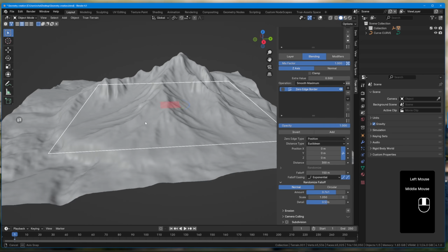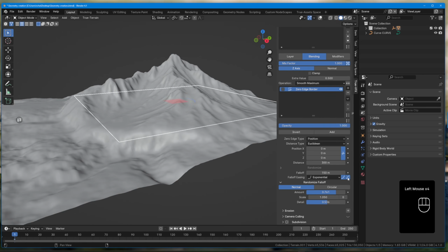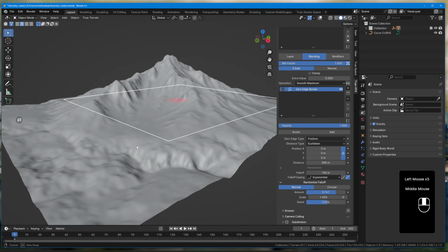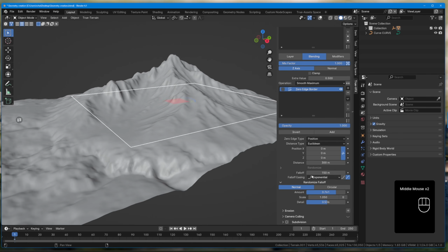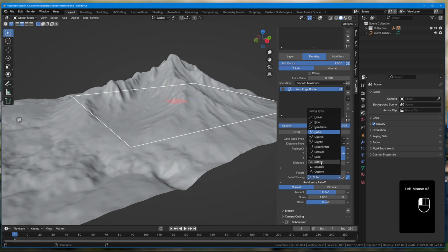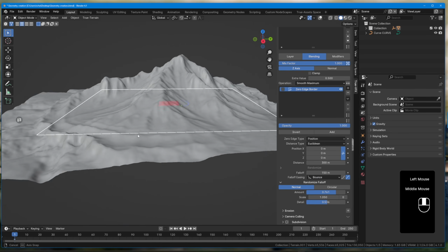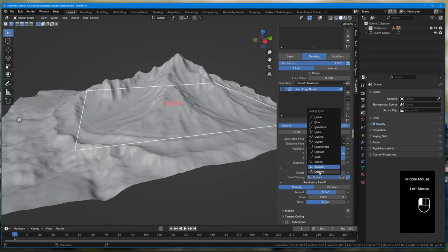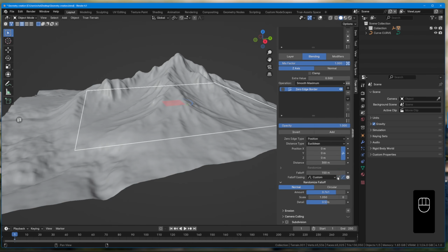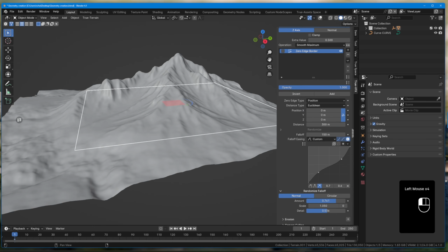So you can see when we added the external handle on, we can see that the distance changes. If we turn that one off, we can see that that softens out. We can go for another type. We can go sine wave, we can go cubic, we can go elastic, where we can see it will bounce back on itself. We can use the bounce function, or you can create a custom one, and a custom one will come up with this new panel, the little cog here. If we click on this, we can adjust how we want that fall off to happen.